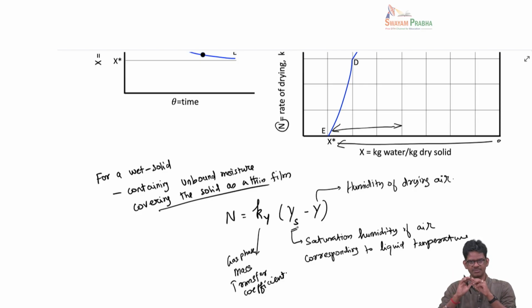But from the concept point of view, during this drying process, heat is transferred from the gas to the liquid, and the liquid evaporates by consuming that heat via latent heat. This process can reach a steady state. At that steady state, the liquid temperature will take a steady value.